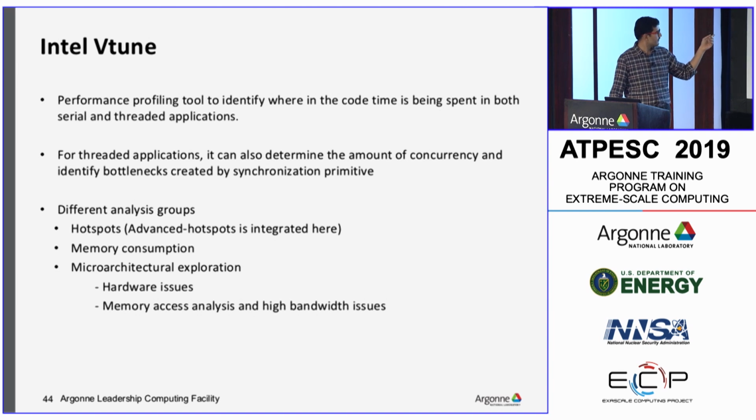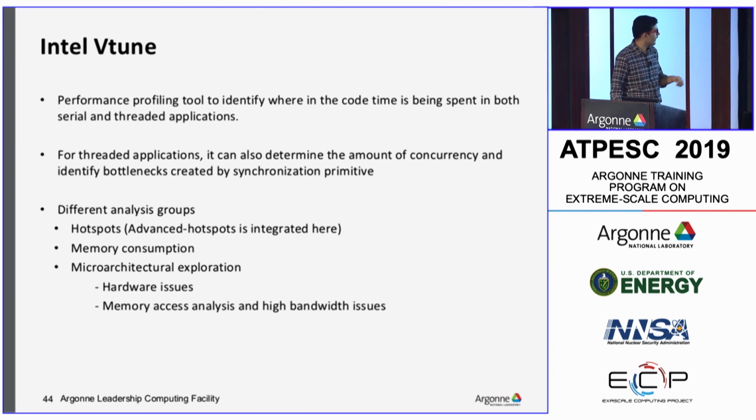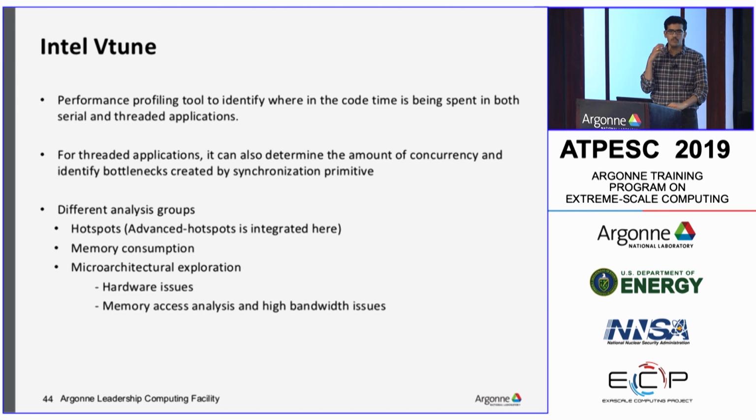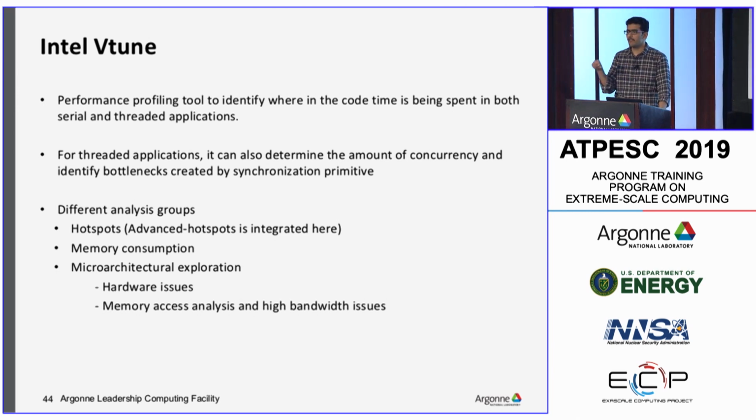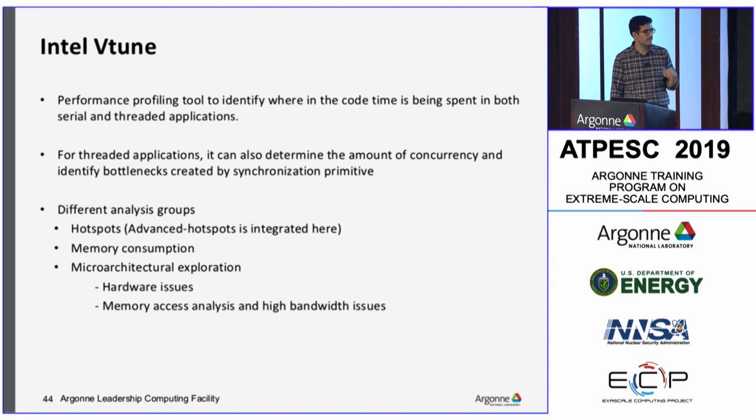The other group is memory consumption. We want to understand how much memory is consumed by the code. And the other group is called microarchitectural exploration. This gives finer level information on the hardware characteristics, trying to understand the memory access patterns and the bandwidth related information.